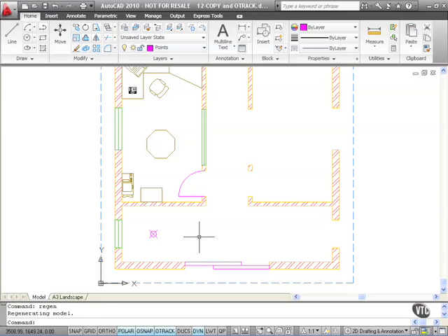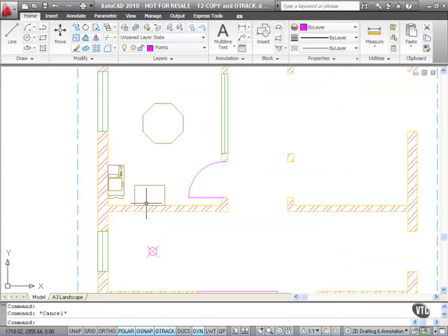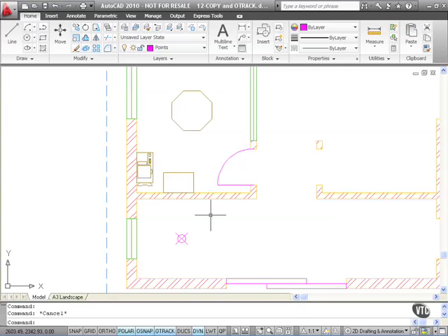You select the object, pick a base point, and I'm going to place the copy there. Now, how do I find a center snap of a polyline or polygon? If I click on that, there is no center grip, there is no center snap. So how do I do it? Well, just pan and zoom a little bit so that you can see both the table there and the point. Little trick here, select your object to copy first. It's quicker. It's called noun verb selection. Noun is an object, verb is a doing word.